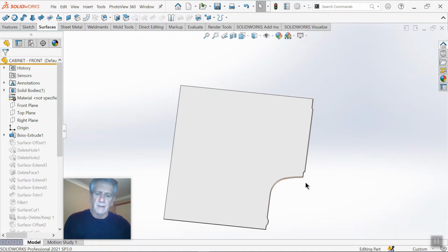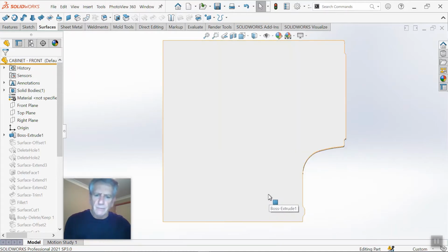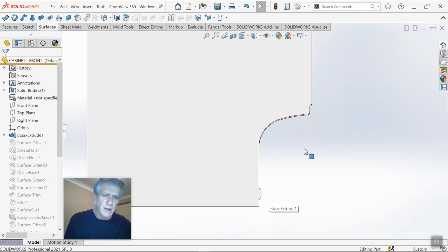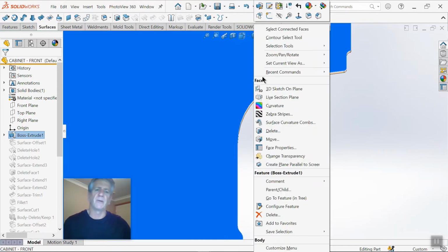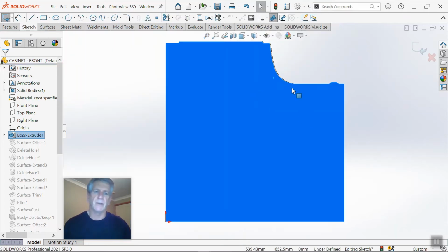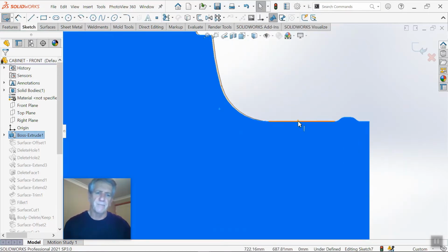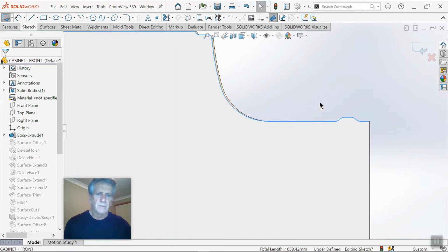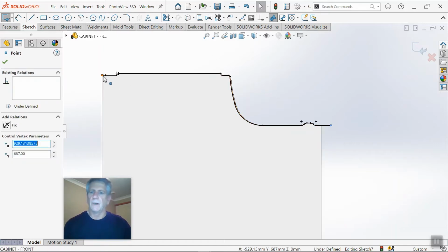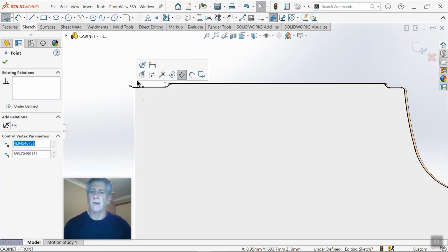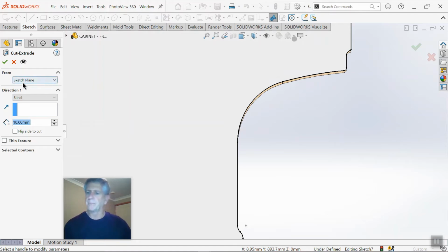So now that I have that set, you can see that we've got an angle, and normally I would then just finish that up because we're going to cut this on a CNC one day. So we're just going to select that, select tangencies, just do an offset and a bit of a drag for those, and then I would normally just do a cut through all.